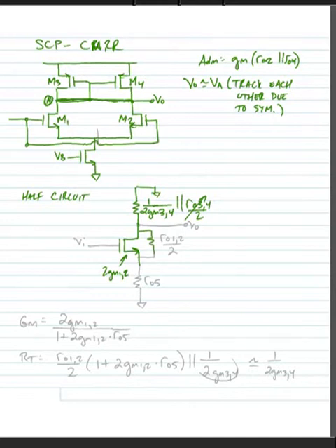The output resistances of M1 and M2 are effectively in parallel, so we can say that the output resistance of 1 and 2 are divided by 2. And finally, we look down towards the tail current source, and we see that tail current source ro5. So our input is here, VI. Our output is in the same position that it was before, VO.